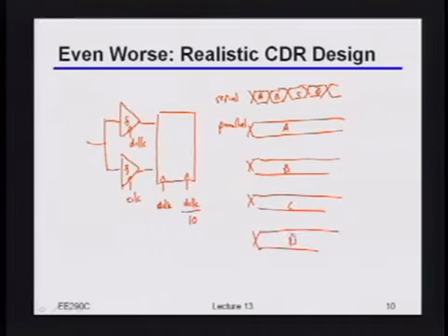So I'm taking this high-speed serial data, and instead of having 12 gigabits per second on one wire, I could have 1 gigabit per second on each of 12 wires. Obviously the net throughput is the same. It's just that now I'm translating it to a lower individual sample rate, but with more parallel wires.